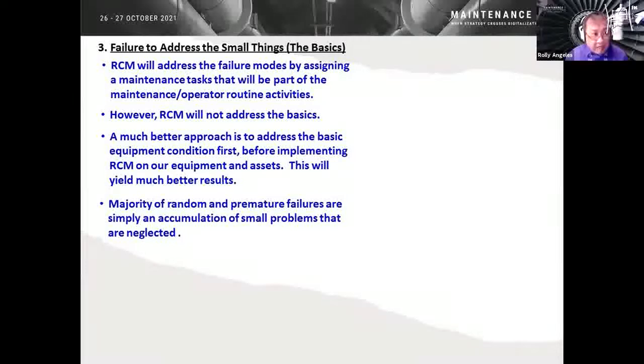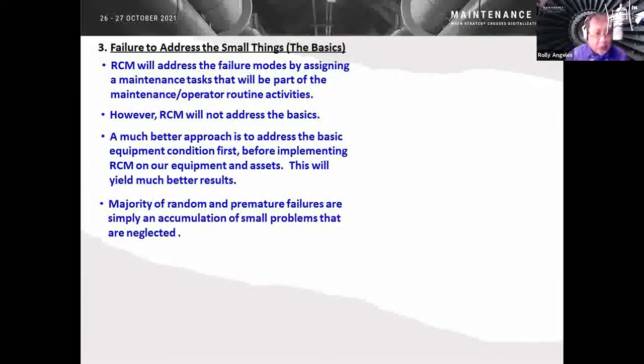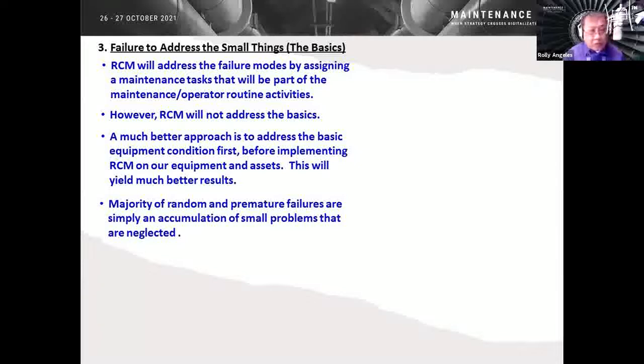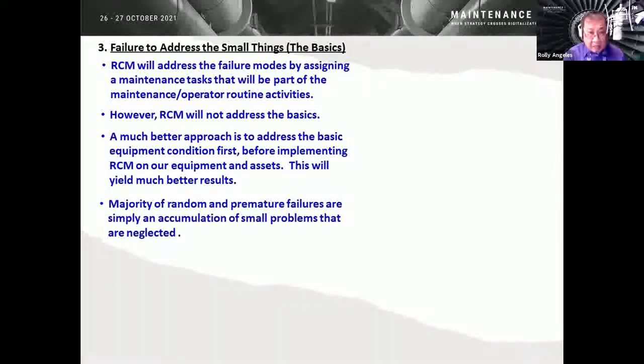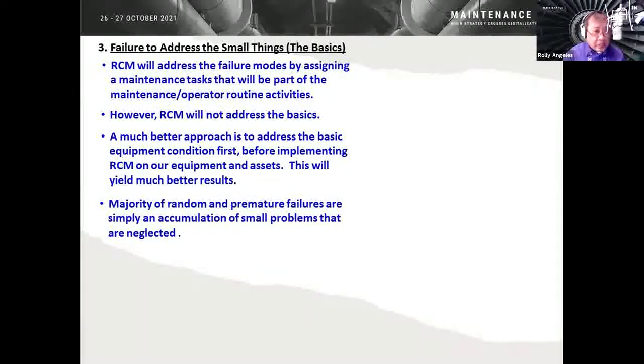Definitely, if you lack a single bolt, you can expect the vibration to increase. And the majority of the failures, most especially random and premature failures, are just an accumulation of small problems that we try to neglect on our equipment and assets.